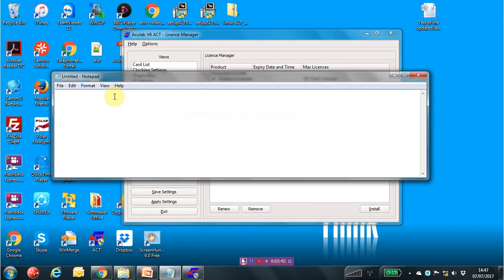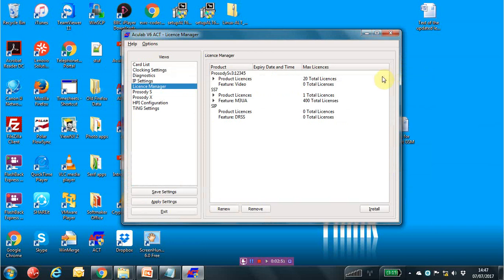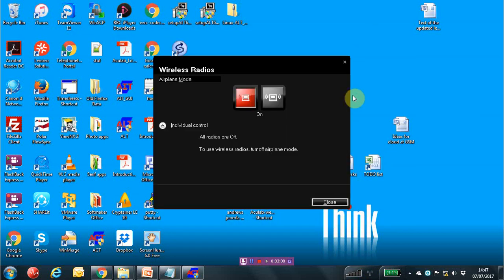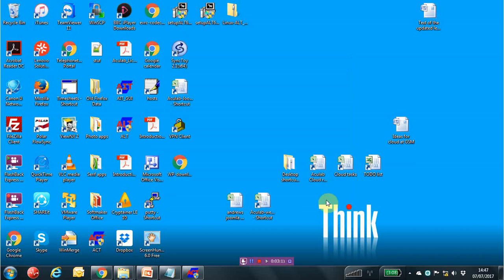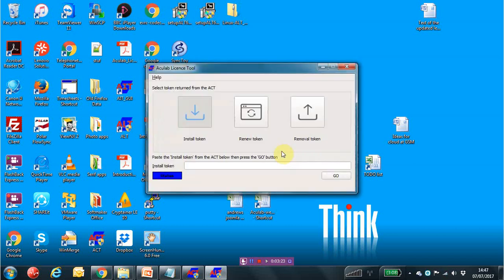That was the previous one. So if I put that string into here, at this point it's a delete string. Right, so what I now want to do is use the ALT to tell the Acculab license servers that I've deleted that string from this offline server. So I need to go back online first, because I'm doing everything from this laptop, so I'm having to toggle it on and offline. Now I fire up this tool, the ALT, which you download from the Acculab website, as I said earlier. And there it is.